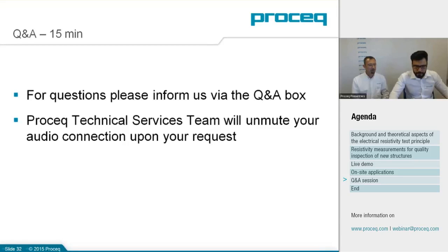I got a question about using the instrument for making proofs in the recent element of construction without considering testing in cylinders. I came from Bolivia, where environment conditions are totally different, where the ACI standards. Okay, it doesn't mean that resistivity doesn't have a qualitative meaning, and what's most important, an aerial mapping of the surfaces. So there are reference values for different type of concrete. We can provide that, and anyway, the criterion will always be to define homogeneity. You cannot assess anything in terms of absolute thresholds in this case, but sure it will provide info about the building.